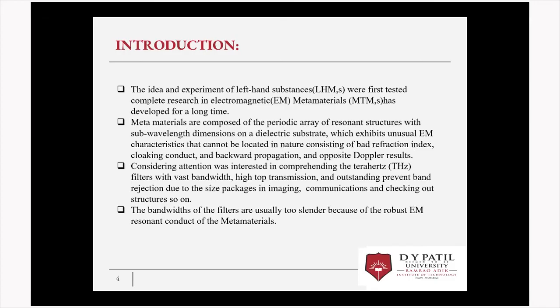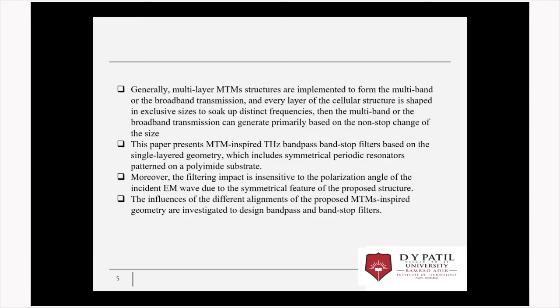Metamaterials are also composed of a periodic array of resonant structures with sub-wavelength dimensions on a dielectric substrate. Regarding the terahertz region, considerable attention has been given to it, because it offers wide bandwidth, high transmission, and outstanding rejection level for imaging and communication purposes. This paper presents a metamaterial-inspired terahertz bandpass and bandstop filter, with the two responses obtained in a single layer geometry.